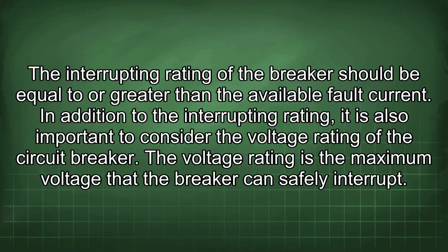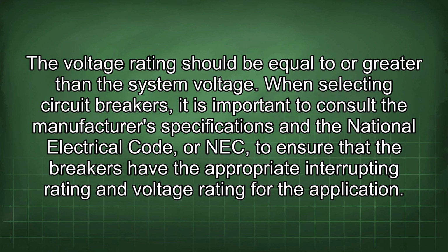In addition to the interrupting rating, it is also important to consider the voltage rating of the circuit breaker. The voltage rating is the maximum voltage that the breaker can safely interrupt. The voltage rating should be equal to or greater than the system voltage.